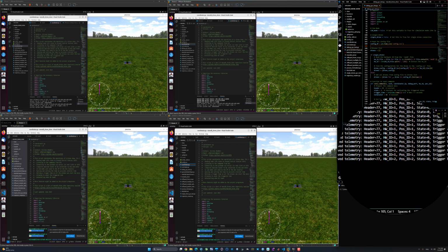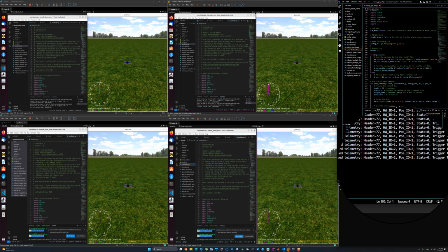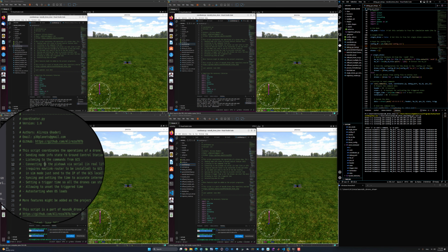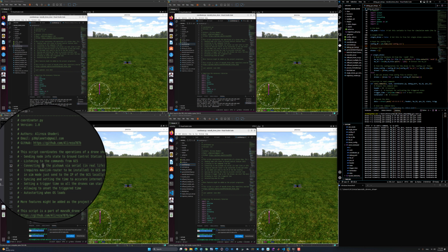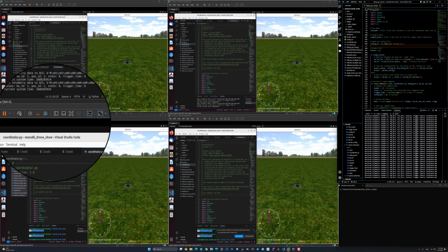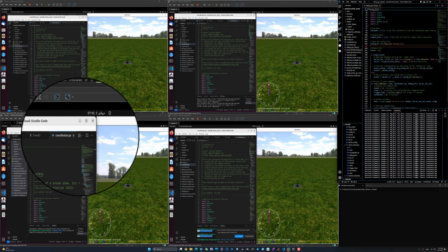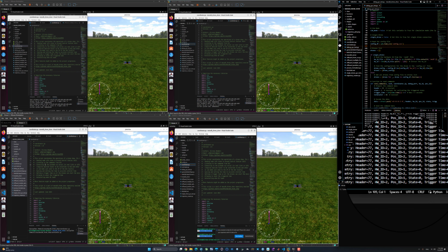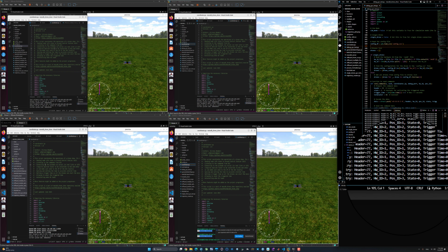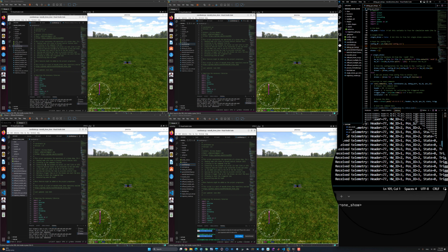And here it is. You can see now we have one packet from ID 1 and one packet from ID 2. They are sending with a sample time of 2, so every 2 seconds we get a telemetry packet. Now let's run the coordinator for drone 3. And now we should have telemetry from ID 3 as well. Here it is: 1, 2, 3, again 1, 2, 3, and so on.